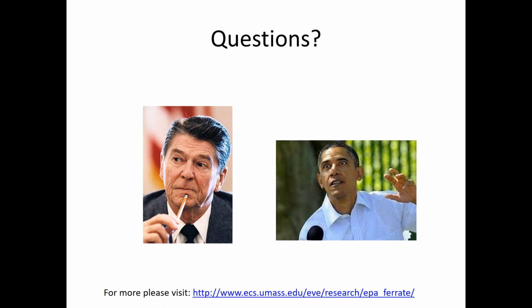Okay, thanks. Here's a couple more questions from Todd. Is it accepted at this point to use ferrate in addition to a standard disinfectant such as hypochlorite, same as the question before? For example, if we were to add a small precoagulant ferrate dose to help control algae growth in our water treatment plant? Yes, absolutely.